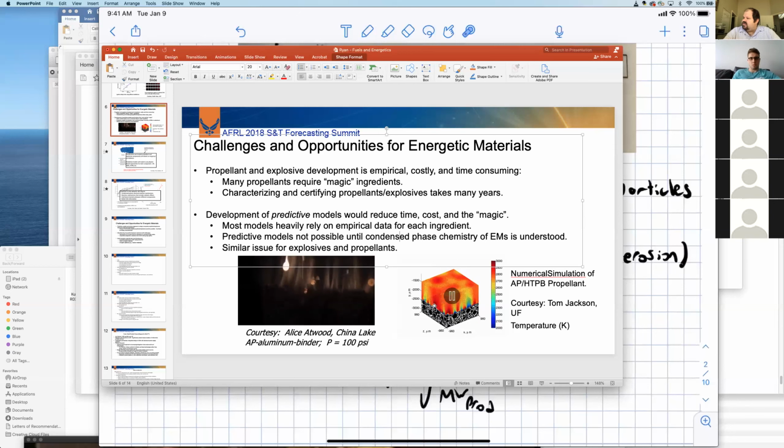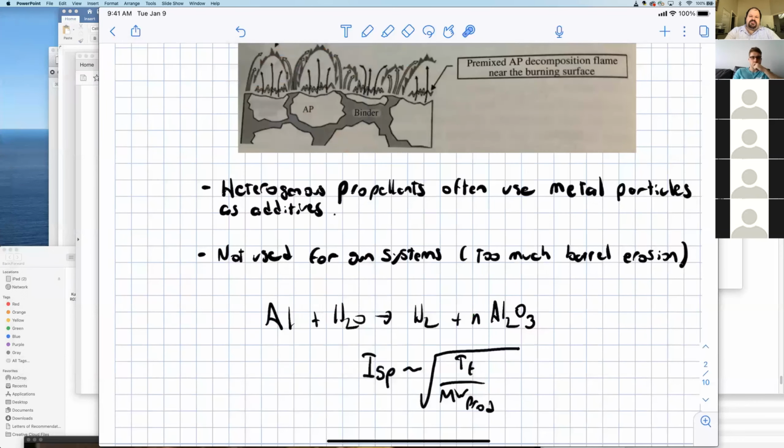It's only with these massive burning crystals that you see that it takes quite a bit of distance on this length scale to burn the composite propellant. And just bear in mind that this whole domain is not quite 2 millimeters wide. So this is very, very small. Most of the AP particles that are used in composite propellants are on the order of tens of nanometers in size. So these are very small. Okay, are there any other questions?